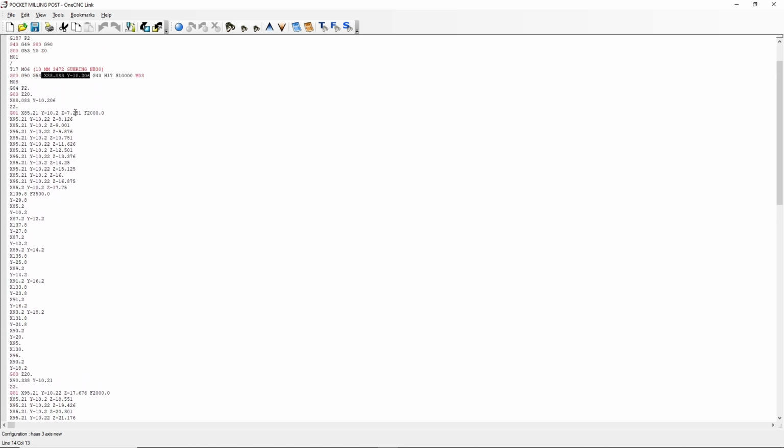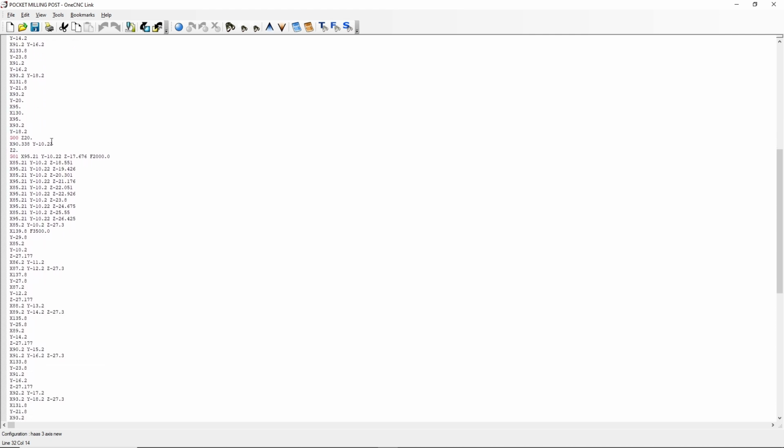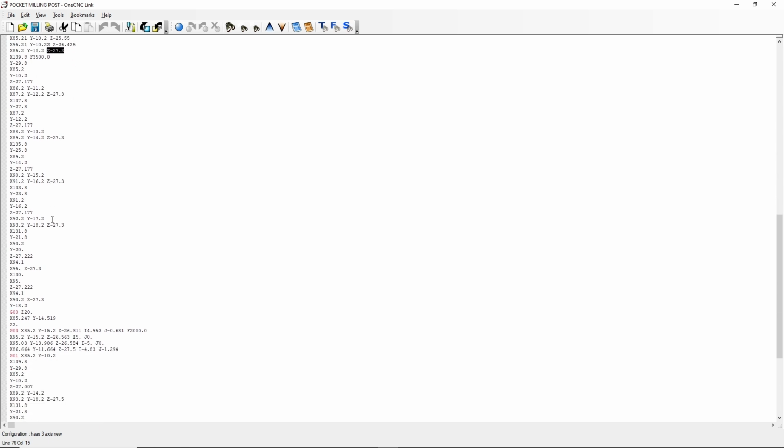So yeah, you can see here, look, feeds down 7.251. So it goes Z20, Z2, and then that's a feed line down to that depth, and then look, you can see it's zigzagging down all the way until it gets to 10mm deep from that face. Right, then it's going to come in and hack that pocket out with a traditional style step over. Then it's going to zigzag down again to the depth that we told it to go. So it's got to hack that out.